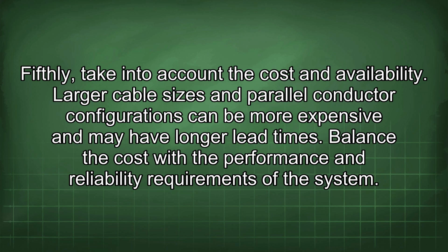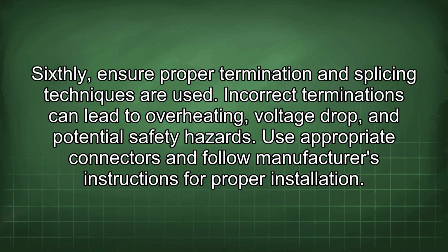Fifthly, take into account the cost and availability. Larger cable sizes and parallel conductor configurations can be more expensive and may have longer lead times. Balance the cost with the performance and reliability requirements of the system. Sixthly, ensure proper termination and splicing techniques are used. Incorrect terminations can lead to overheating, voltage drop, and potential safety hazards. Use appropriate connectors and follow manufacturer's instructions for proper installation.